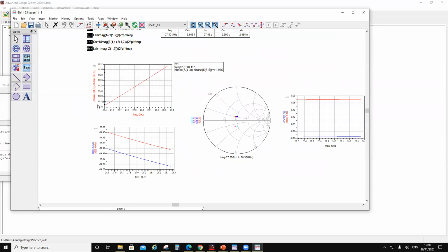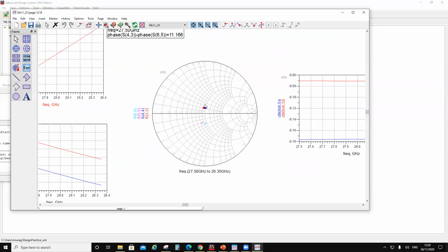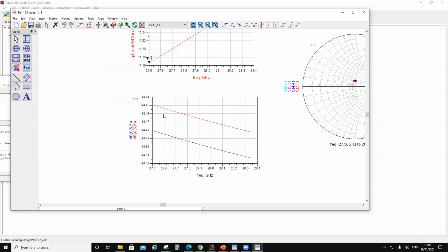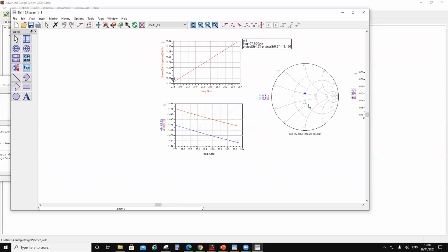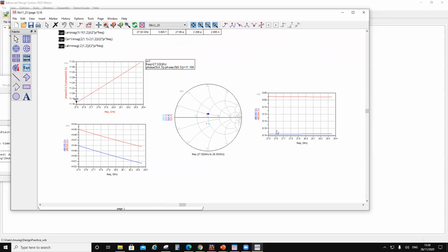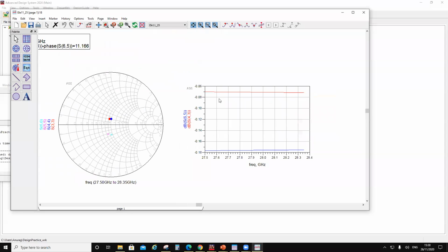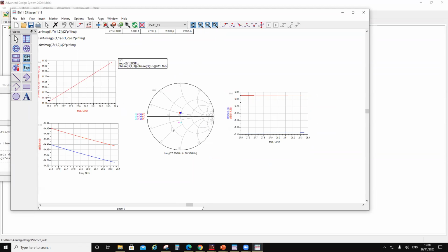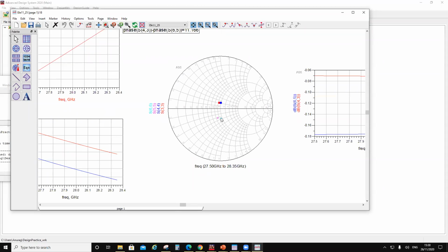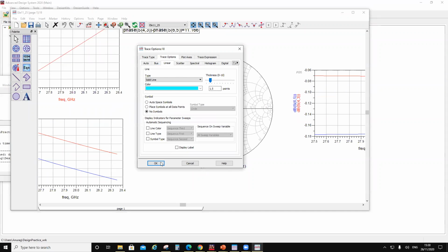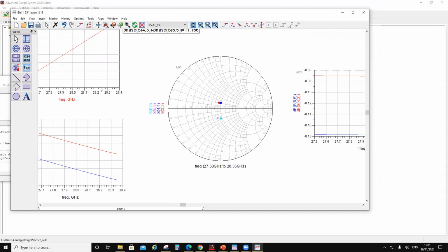Okay, so I'm not going to spend a lot of time on this. I am seeing that there is a delay of 11.25, right? And then there is a mismatch over here, which is better than 14 dB. So if it is better than 14 or 15 dB, of course, there's a difference over here. Again, this difference is not much, 0.1 dB. So now I'm going to live with this. I'm not going to go ahead and change this. Okay, so we will leave it up to here.